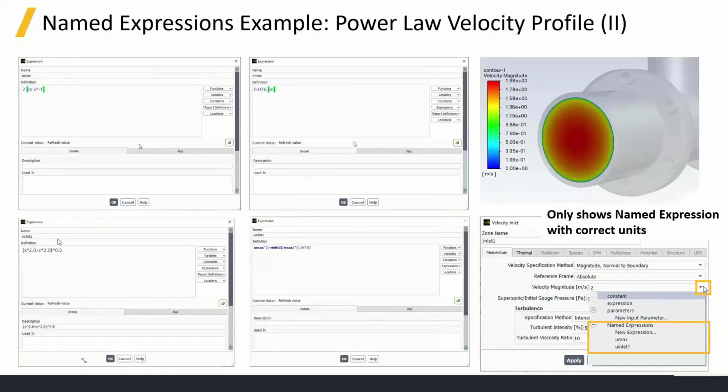We can set our R, our radial component, which is the square root of x squared plus z squared on this particular inlet. There. We can give its maximum value. Although when you do the maximum radius here, we could actually have been smarter and done the maximum value of, say, x on that face. And so we wouldn't need to change this number if the pipe diameter changed.